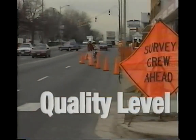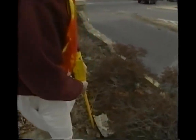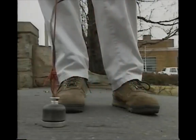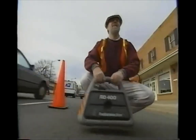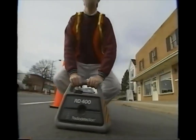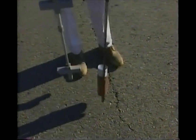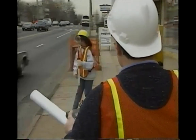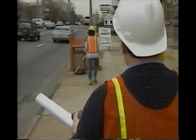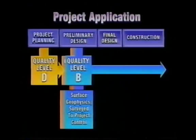Quality level B is the first level where subsurface utility data departs from traditional practices. It involves supplementing quality level D information with designating, surveying, and mapping. Designating is the use of surface geophysical prospecting and remote sensing technologies to determine the existence of underground utilities in plan view. The use of this information allows decisions to be made during the preliminary design phase of a project